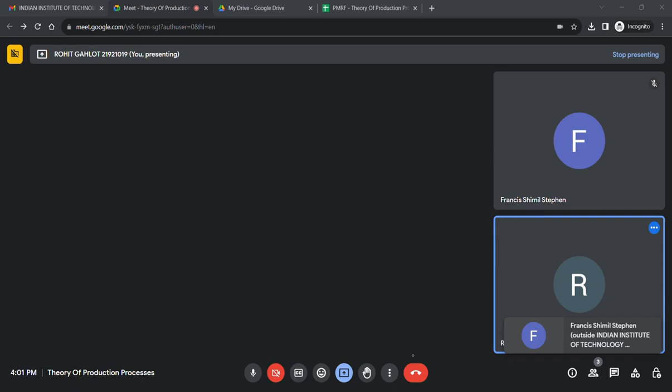For the top riser, as it is installed this way, this area won't be useful in any heat transfer, so only these three surfaces will be helpful. While in case of a side riser, as it is installed sideways, both the bottom areas as well as the peripheral area are useful. That's why two times this area plus this area. Okay, sir.